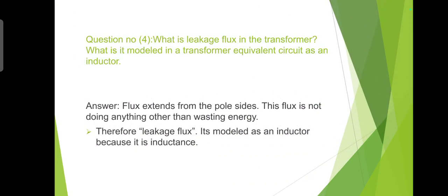Question number 4. What is leakage flux in a transformer? How is it modeled in a transformer equivalent circuit? Answer: leakage flux is flux that escapes from the core, which is not doing anything other than wasting energy. Therefore, leakage flux is modeled as an inductor.